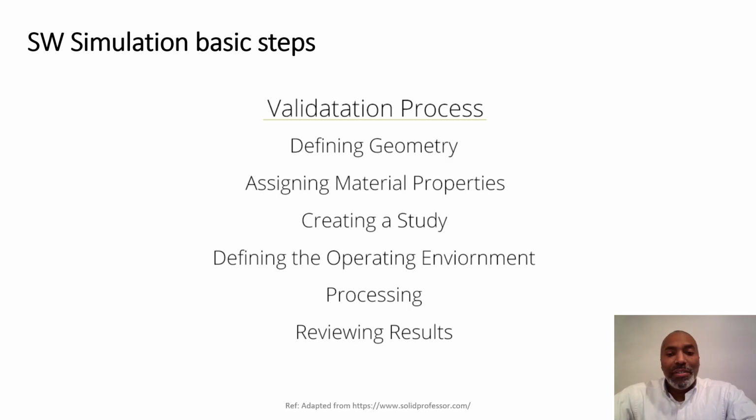So after we've defined our geometry and assigned our material properties, then we do what's called creating a study. And this study is kind of a misnomer. It's not a verb, it's a noun. We're actually going to create a study where that study tells the software, here are the physics that you're going to use, here are the governing equations you're going to apply, and here's the solution method you're going to use. Once we know those things, the software goes off, it does its thing, and then it gives us back a solution. Well, actually, let me say there's one more step in there after we've created our study.